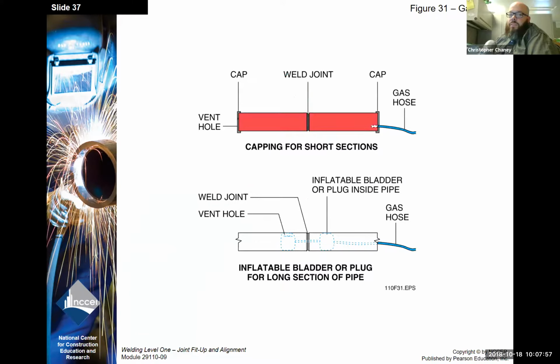All right, gas backing. This is a system that's done when they weld mainly stainless steel, like food grade stainless in food processing plants. So the gas shielding is inside the pipe. You purge all the oxygen out. You're welding from the outside, and that shielding on the inside allows you to have a nearly flawless weld on the inside of the pipe, as long as it's welded correctly.